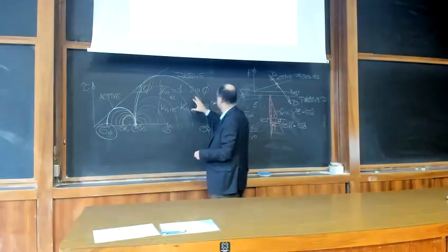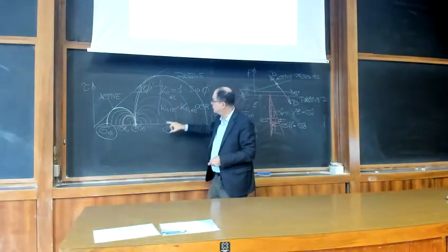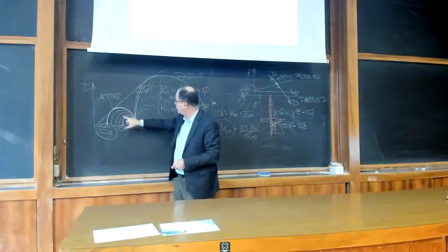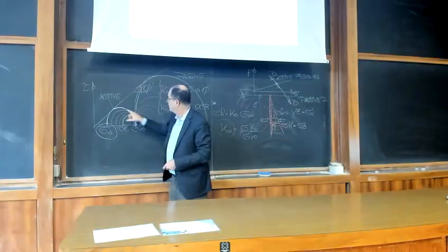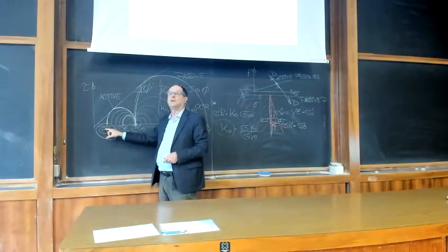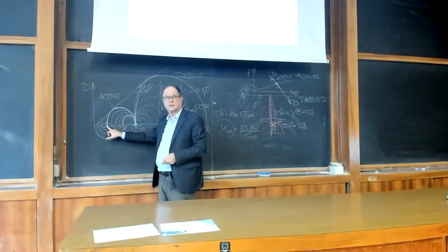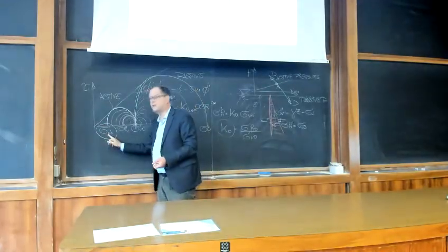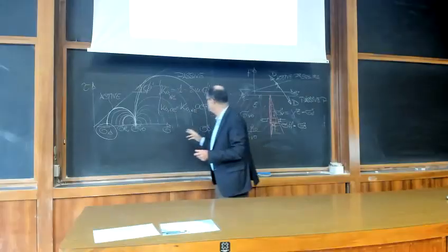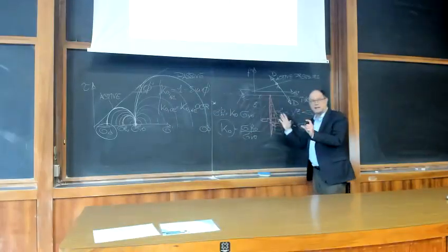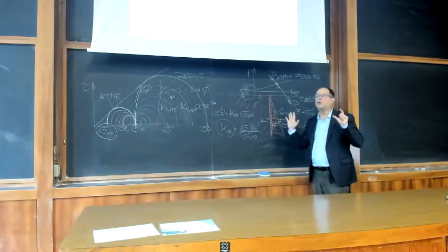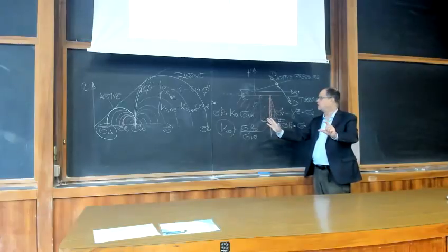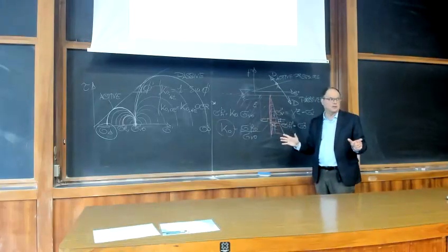It's no longer like this equation of K naught, because we know this, we know this, we know the tangential condition, and so we can determine this, and we will see now in a minute. So we can define these active conditions as conditions at failure, when the wall has moved laterally until it gets to failure.